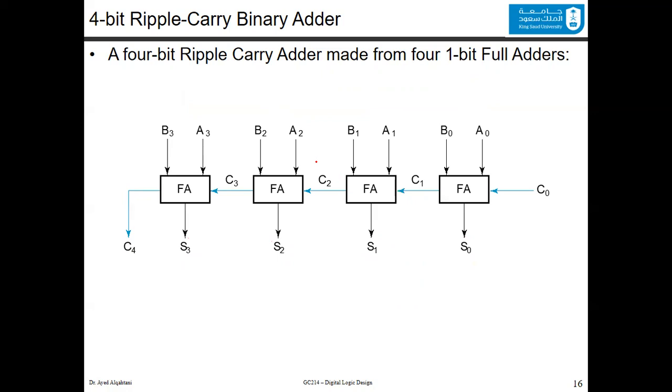This is a ripple carry binary adder, and this is the first type of multiple bit addition. It's very famous because the design is very simple. The idea behind it is just connect the carry output to the carry input.